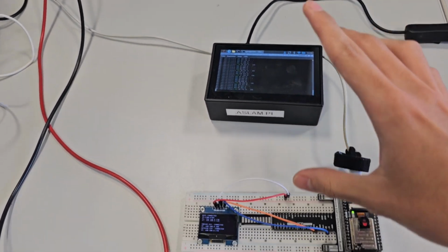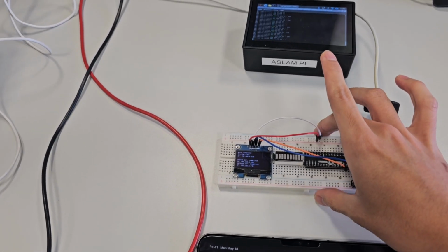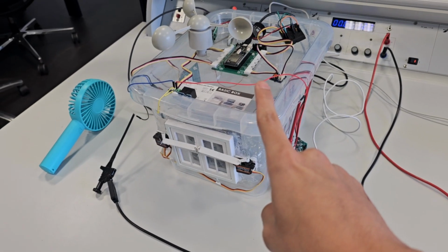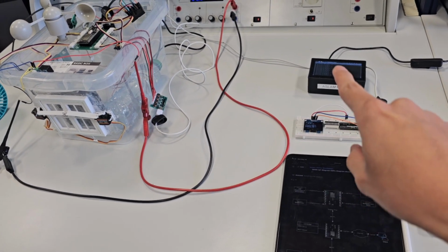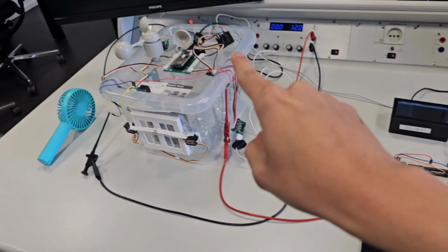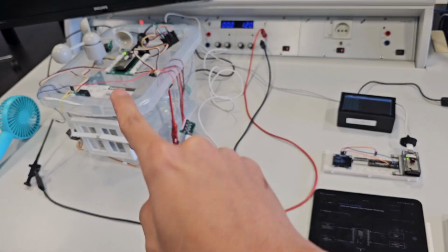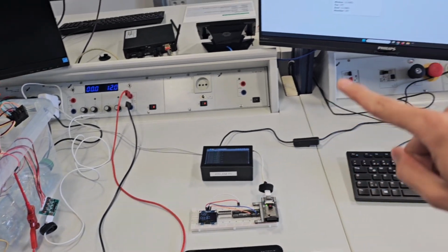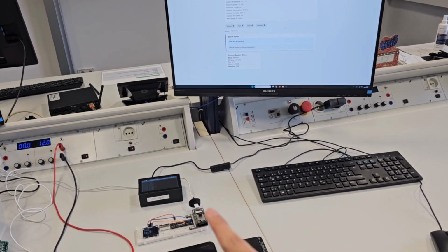The web server sends it to the communication center, and the communication center passes it along to the ESPs around here. The communication between the ESP communication center and the indoor and outdoor ESPs uses the MQTT protocol, and to the user it uses the HTTP protocol.